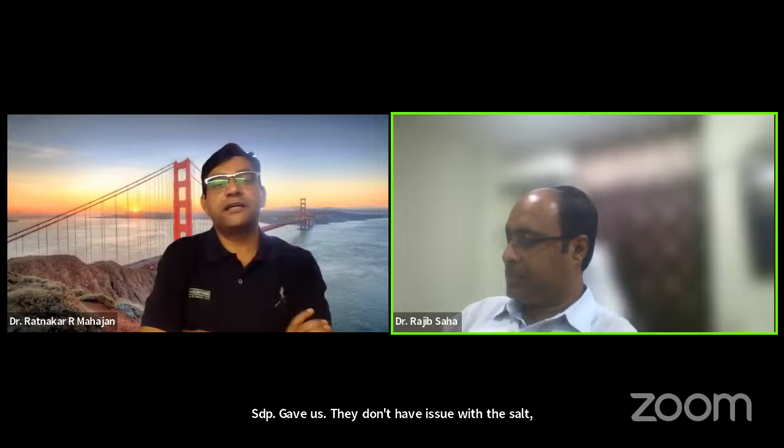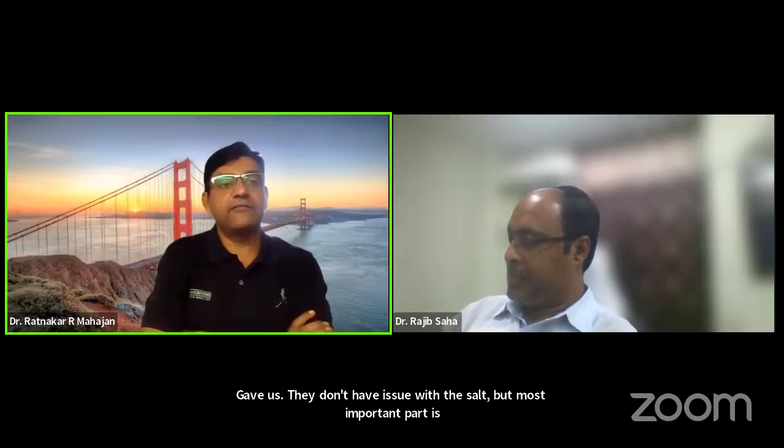So HDPE gabions, very good question. HDPE gabions don't have an issue with the salt, but the most important part is that HDPE is a polymeric material and it will degrade over a period of time when it is exposed to environmental conditions, typically UV rays. So HDPE will not have any issues related to the salt, but yes, it will degrade if it is exposed to sunlight.